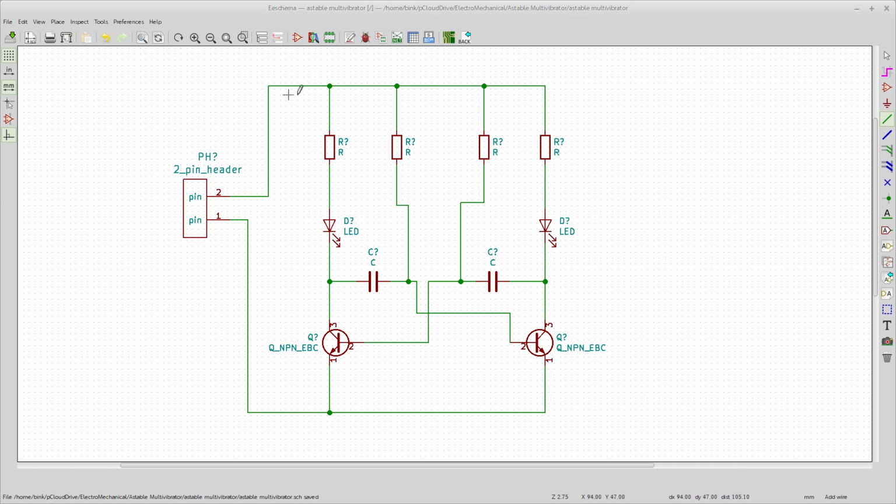Everybody knows that those are all going to be at VCC. Why the hell did you do that? Well, maybe you didn't know that. Maybe you never got that proven to you, and you want to make sure that it's a fact. Maybe you just did Kirchhoff's voltage law, and you want to put a test point right down here to check to see if that's at 0 volts to ground, even though it's horribly obvious to most people that it probably is. Throw one in there anyways, okay?